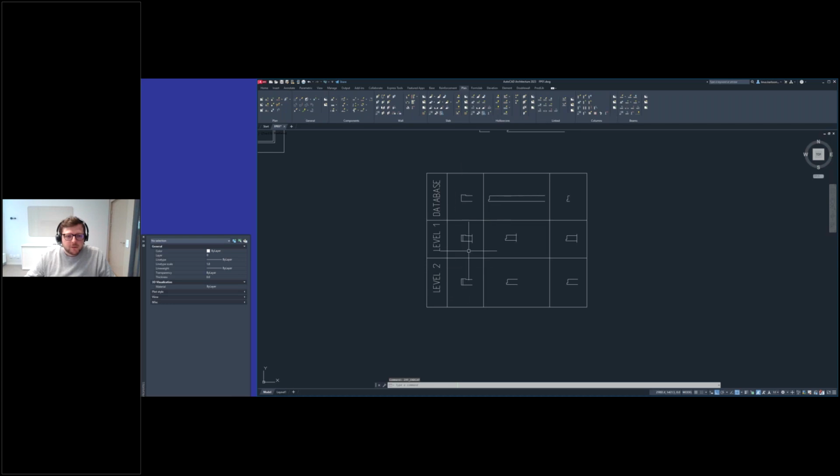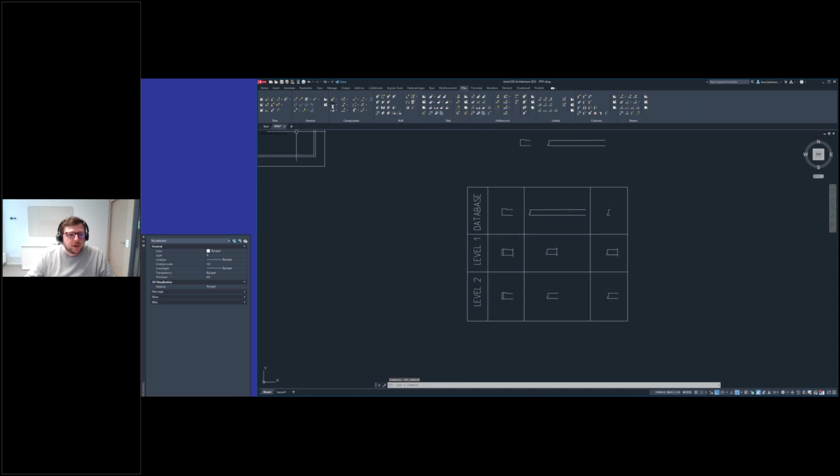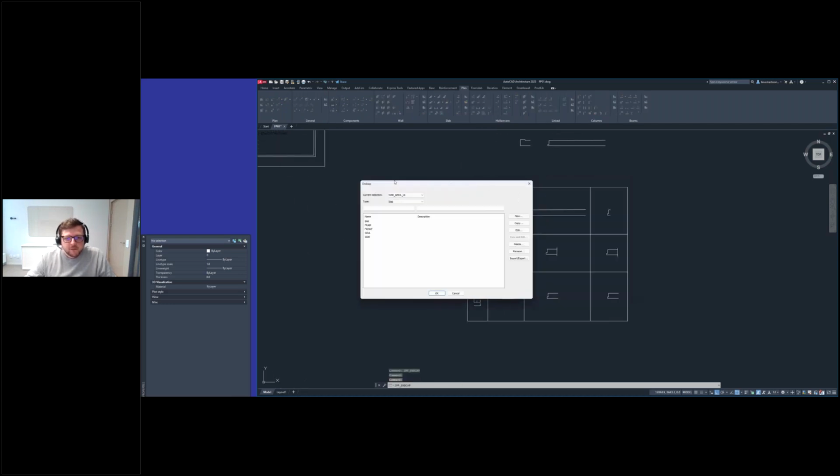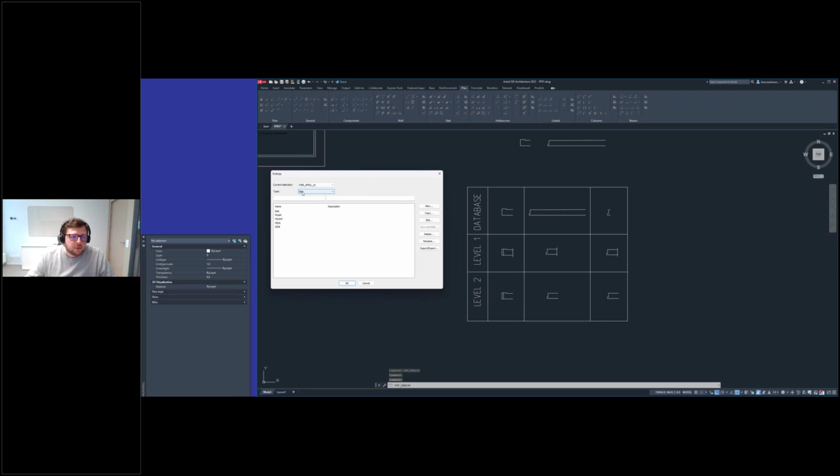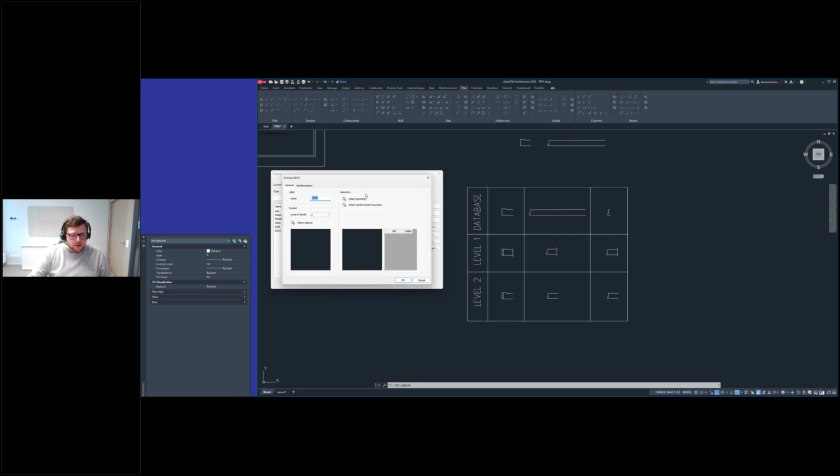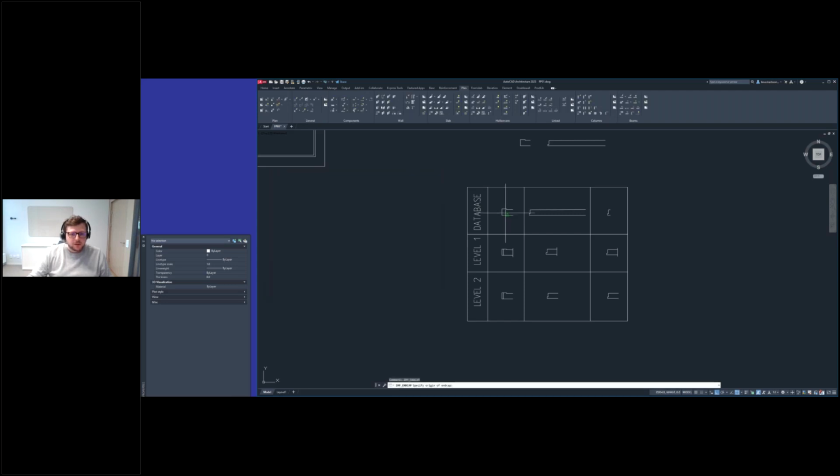So the back end cap is this one. So let's do that together. It's very simple. You need to make sure that you're in a slab end cap. Click new, and I will call mine back. Then I will select the geometry.